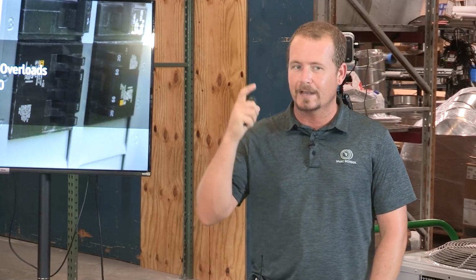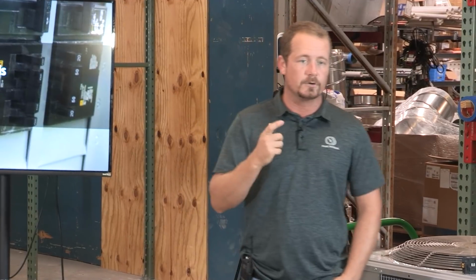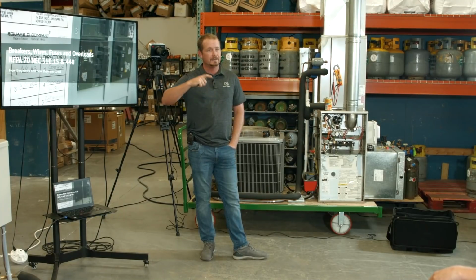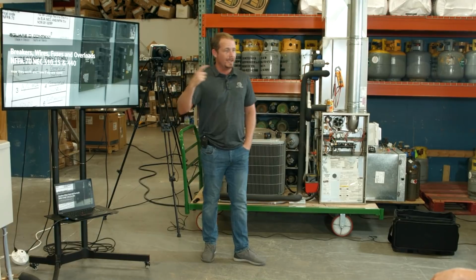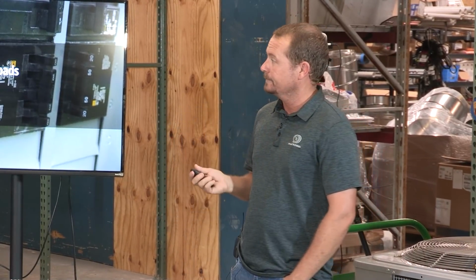So there's a lot of unique things, nice, easy exceptions that we get in air conditioning that makes, in the end, a lot easier, but also creates a lot of heartache when professional electricians don't pay attention to section 440. And they try to apply the other NEC standards without looking at 440, and they think we're doing it wrong, when in fact we're usually not doing it wrong. This is one case where often AC guys actually aren't doing it wrong, surprisingly.